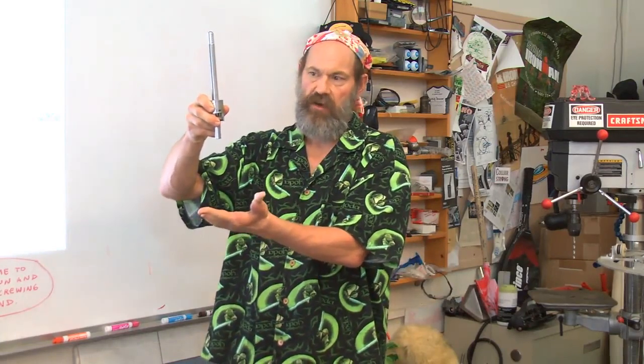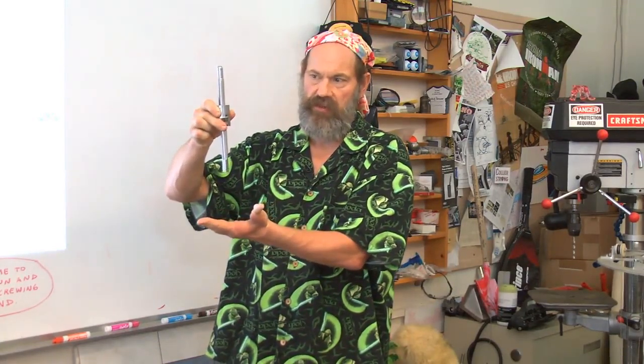This kind of screw in a machine means you got to be very careful on a vertical axis, because when you take off the brake, let go of the brake, or stop holding the motor power, the machine will fall. If the machine is powered by a lead screw, it's not so efficient, but if the motor stops, boop, power of the motor goes out, it's not going to move. So there's where friction can be your friend. Remember, reciprocity, the yin and yang.